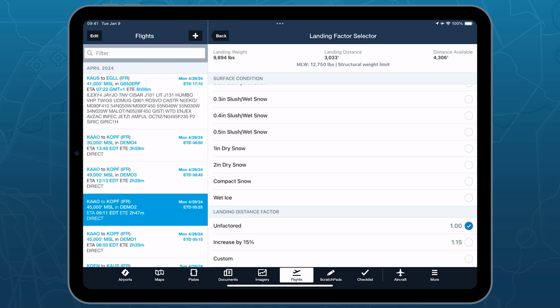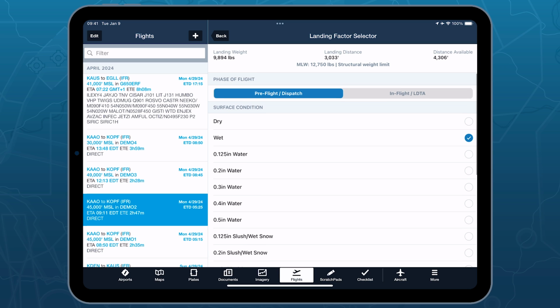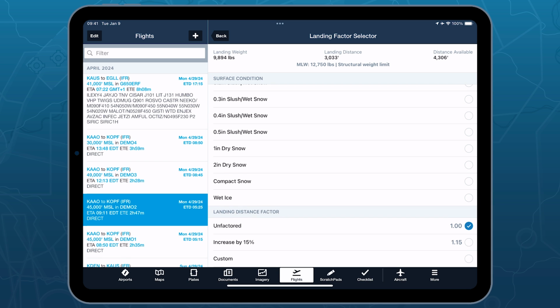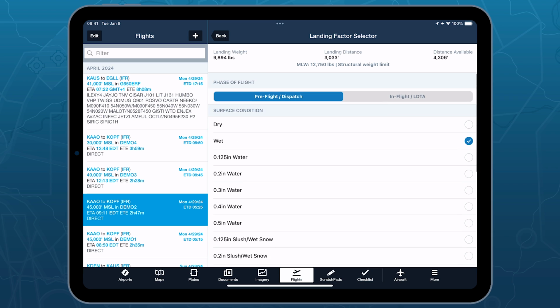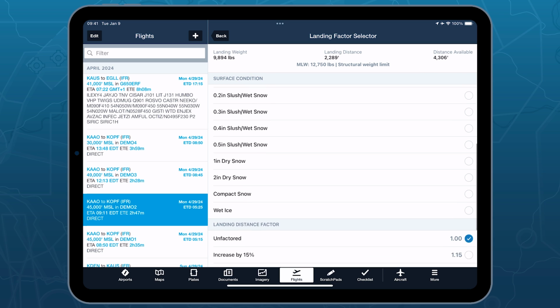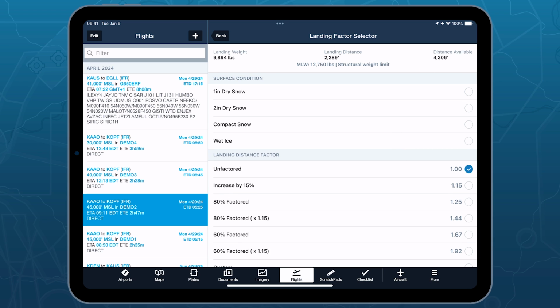We chose to do this on purpose because during the dispatch time of landing distance planning, it is not normal, it's not usual to select a wet or contaminated distance and then factor that in addition with an 80% or a 60%. If you go back to that AC 91-79B, it will instruct you to select your dry, unfactored landing distance as the basis for your factoring down here.